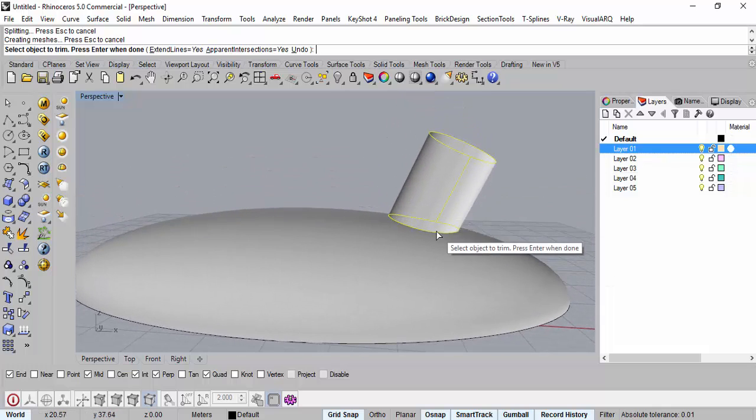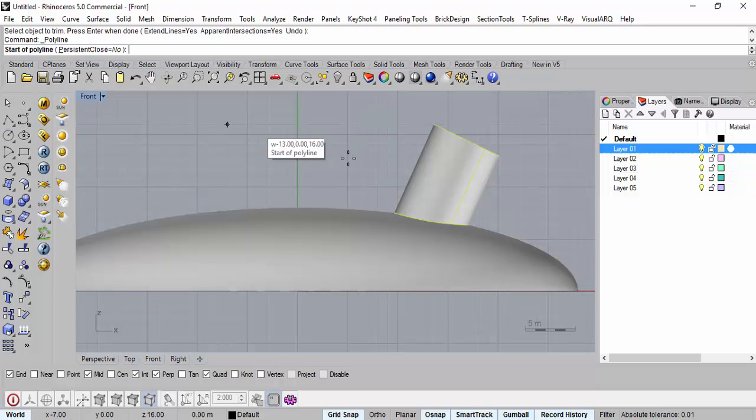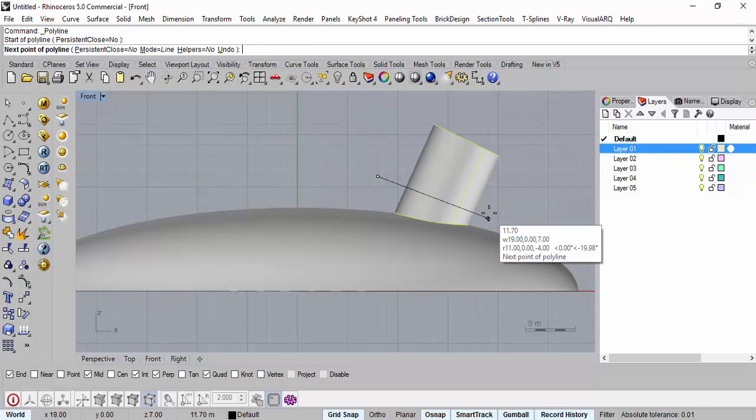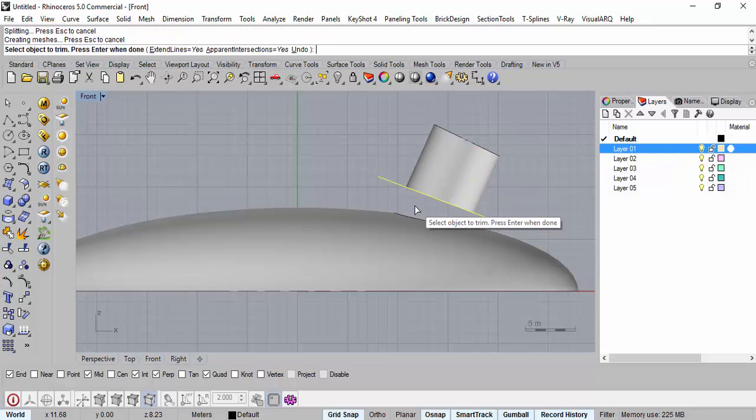Here we need to have some space because there is going to be a curvature coming like that. So you get a smooth blend. Right? So you require a space here. So we'll go to the front view and we'll just cut away this using the same method we used earlier. Just draw a line and use our trim command. Trim away that part. Right?